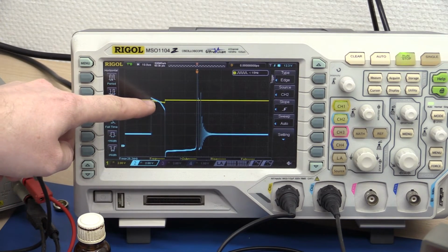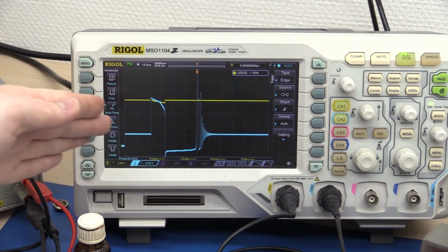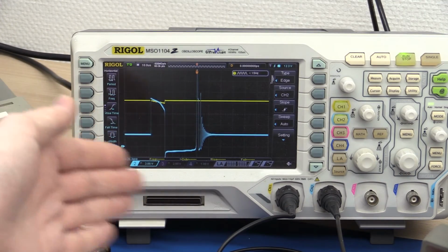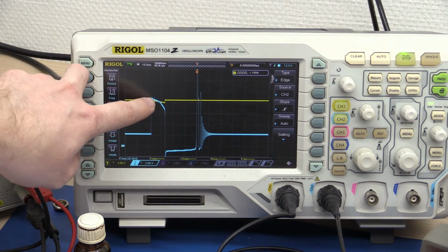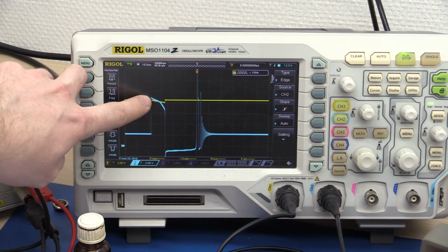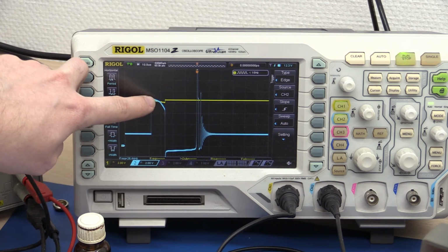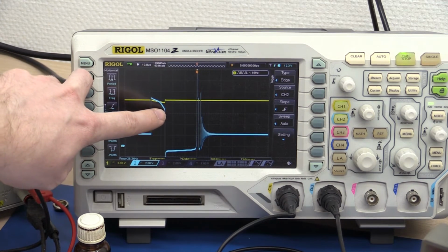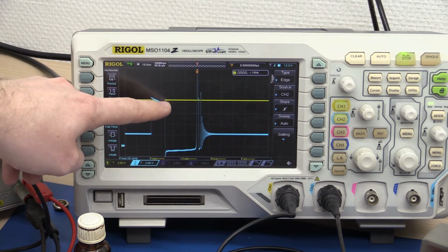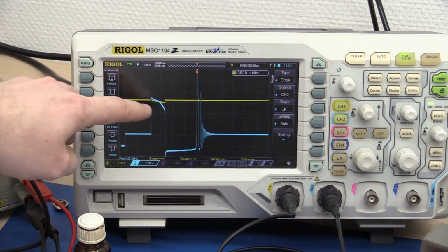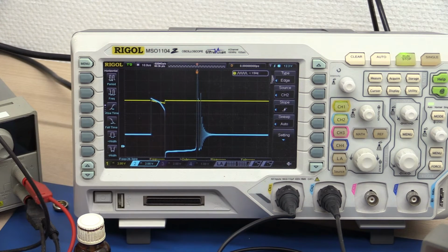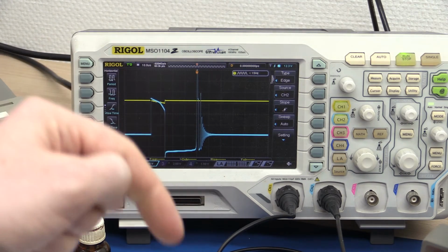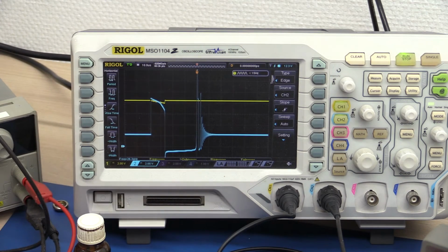It does go to VCC in the beginning, when it starts to push current through the inductor. It's like an open circuit when it just starts. But when the inductor starts to conduct, we have a drop across the transistor. And that's what you can see, the blue waveform dropping here. And the part that's missing from the square here, that is losses. But you can also see that the VCC drops as we start to pull current, and that is because of resistance in the wires and in the breadboard, and that also gives us some losses.